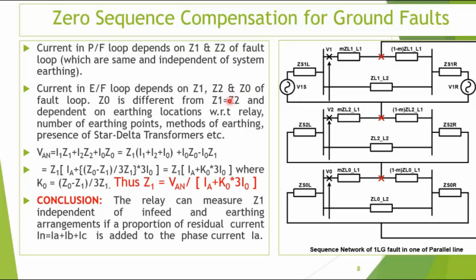When you do distance relay calculation, you will find that the manufacturer gives two values. One is the positive sequence value and one is the zero sequence value of the conductor. The zero sequence value is almost 3 times the positive sequence value, approximately 2.73 times.